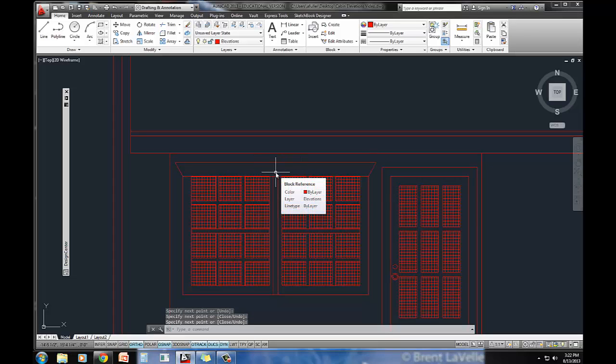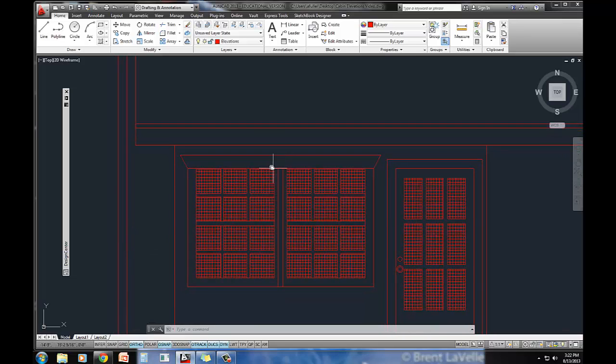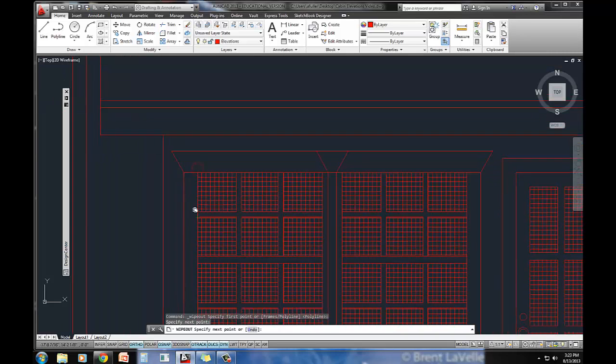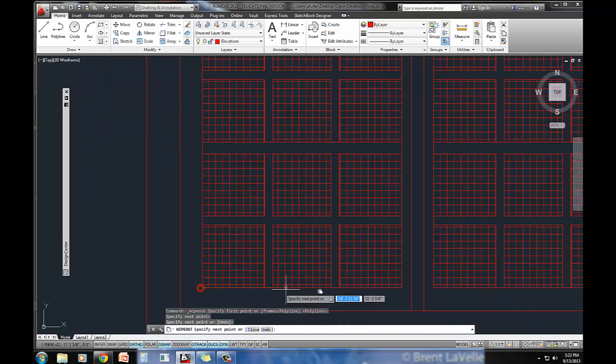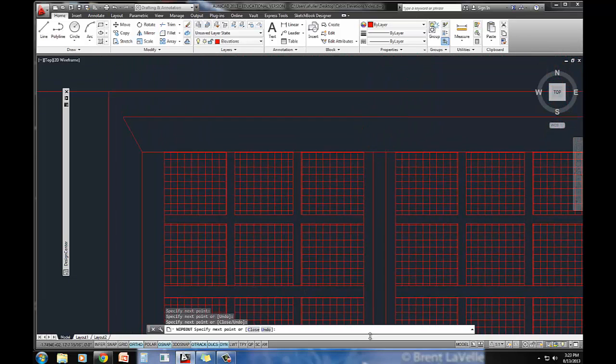It basically just drew a little shape exactly where I told it to be, but it hid what was behind it. And it's not that that's not there anymore, it's just hiding it. So I can do that, and let's do one more right down the middle of this window. How can we do this? This might be a little more tricky because that wipeout is going to leave its own line here. But if we just go around the corners of these windows,